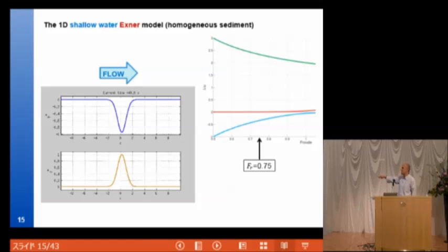So the first fast wave is related to this eigenvalue, to this characteristic. And this is actually the other one. This is negative. It is the one propagating in the upstream direction, and the bed essentially is moving with this velocity, which means that you can see here in this region it is traveling much slower than the other two waves.